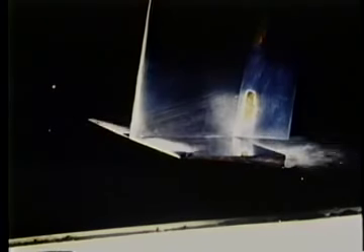The cavity grows when the angle of attack is increased. It also grows when the ambient pressure is reduced. We are lowering the pressure by dropping the water level above the foil by means of an upstream sluice gate. The cavity also grows when the water speed is increased.